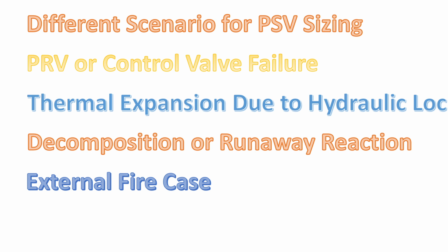Okay, and after a certain time, the vapor pressure or the pressure built up inside the equipment goes beyond the design pressure. So there are probable chances of rupture or blast of that equipment. To avoid such a scenario, we have to size the safety valve considering the external fire case.